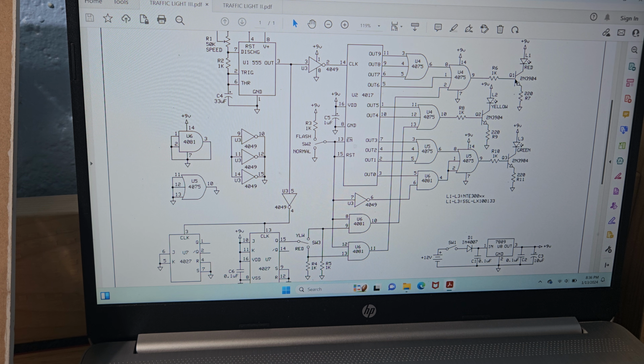Okay, pretty simple. Then the outputs of the OR gates drive a transistor, which is tied to your LED, which I'm going to use. These LEDs are rated at 20 to 30 milliamps. I wanted something brighter, so I got to find some. I want them to be bright so you can see them more in the daytime. So this is your transistor. When the output goes high, it turns on the transistor and it turns the LED on. So these transistors can handle up to I think 200 milliamps. The 2N3904. You see how each output is connected to a transistor to power that LED, because with these CMOS chips, you don't want to try to run an LED straight from the chip. Most of the CMOS chips can handle maybe 10 to 30, but just to be safe, when I do substitute these for the high brightness, I need to have a transistor to get up to 40, 60, 80 milliamps. Okay.